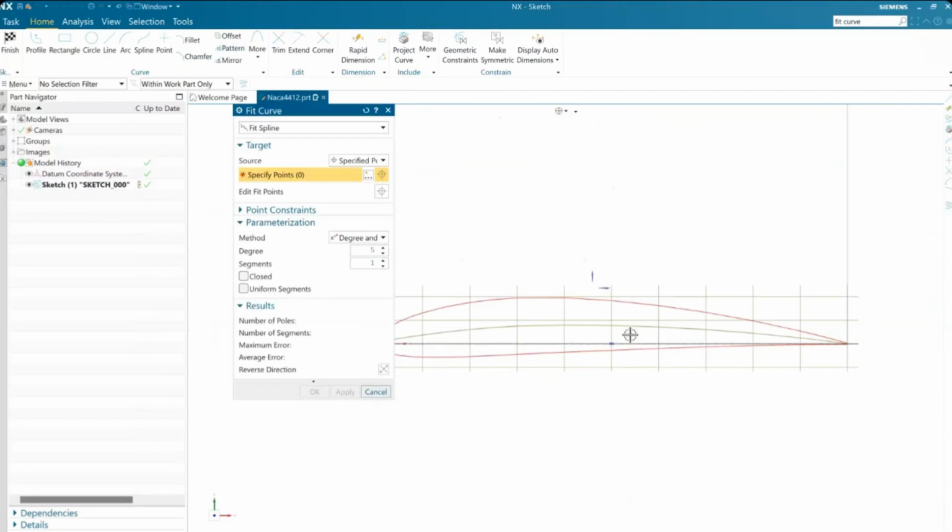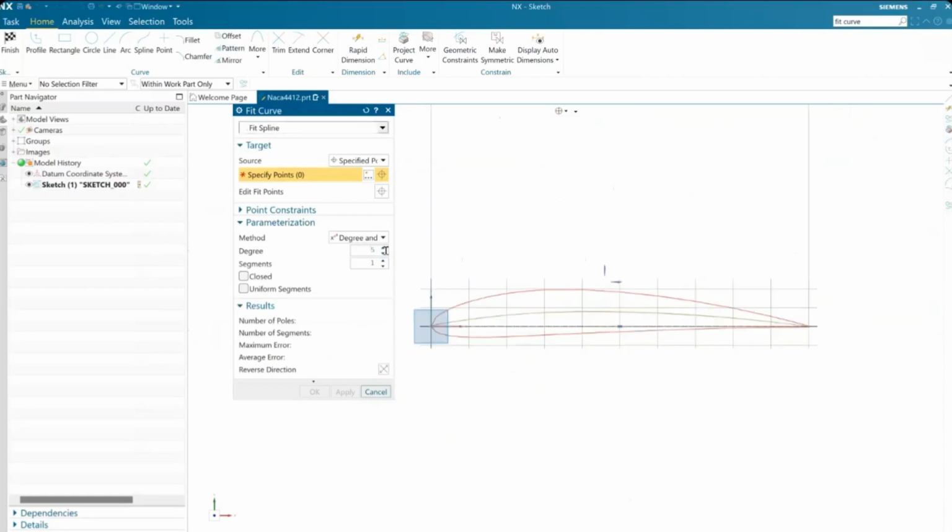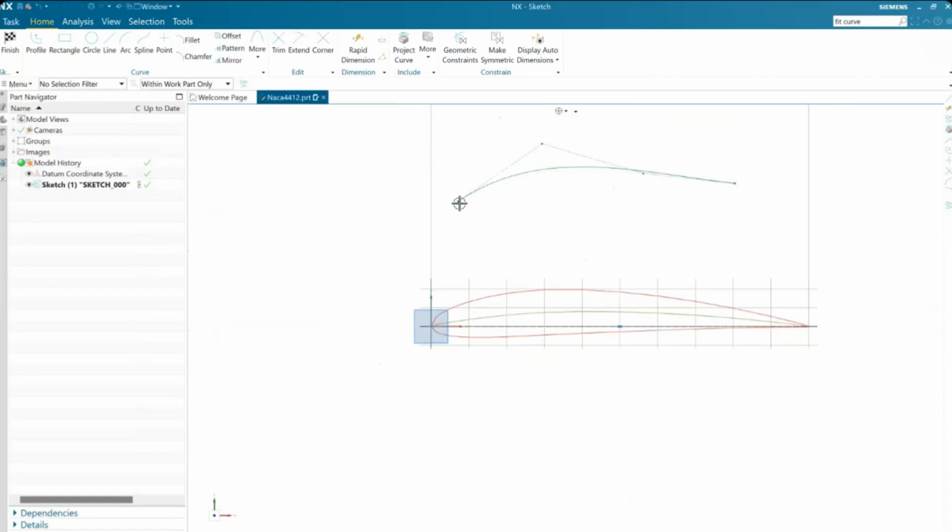Now, firstly, we want to draw this camber line. It's very important that we draw the camber line to get the correct symmetry or the correct geometry of the airfoil. I mean, it's kind of important. It's not important. Never mind. It's very important. So, 3 segments. That means you need 4 points. You'll want one at the leading edge.